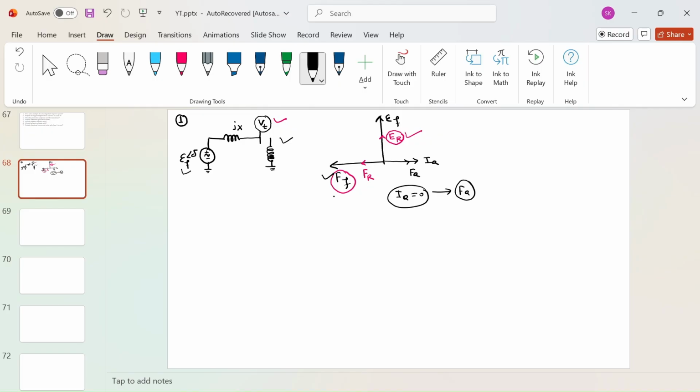So what will happen, because of the highly increased field excitation, your terminal voltage will be tremendously high, and that voltage can destroy the insulation of the synchronous generator. And just now I have taken the example of an isolated case, but think about the power system network. It is an interconnected system, so each bus will be impacted by that high voltage. So if you suddenly disconnect the inductive loads, there will be a rise in the voltage that we need to take care of. Okay, so this is one of the reasons of overvoltage.